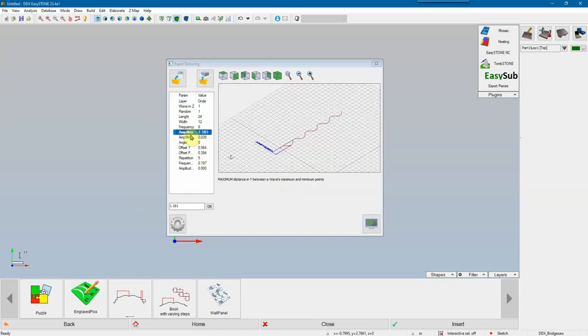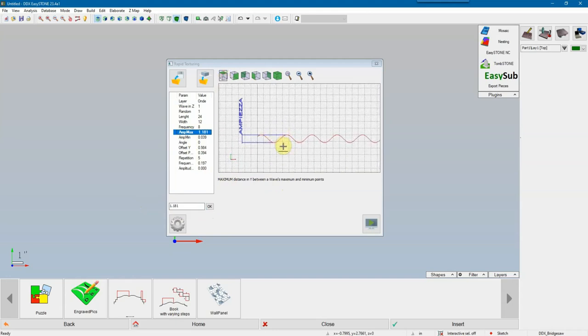The maximum amplitude, again, I'm going to take a look from the top, and you can see a little better that we are describing what is our y direction deviation, the maximum distance that I'm willing to let the software go. 1.8, maybe I want to tighten this up a little bit. 1.18, not too much, I guess. 1 inch I will go with.